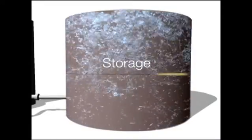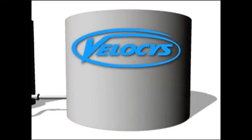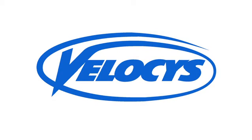The resulting product is an ultra-clean, high-quality synthetic crude. For offshore facilities, this product will be blended with petroleum crude and transported via conventional shipping infrastructure. For onshore facilities, there are many high-value options for FT products. For example, hydrocracking can be employed to maximize diesel or jet fuel production. Microchannel process technology greatly improves the gas-to-liquids process and is just one example of the way Velocys is changing the way the world produces energy.